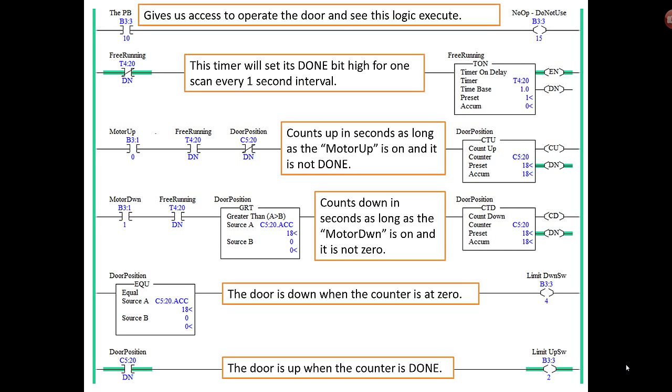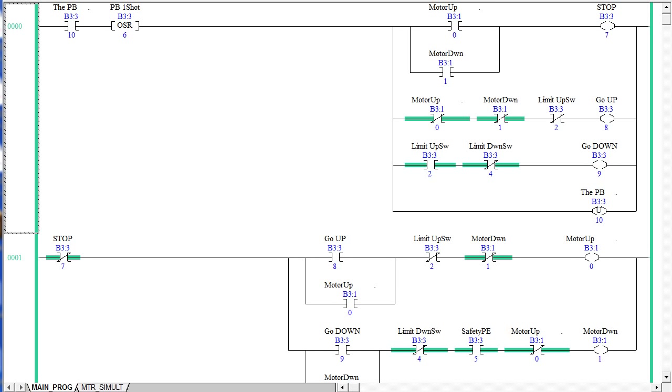So I think what we're going to do now is go to Micro Starter Lite and actually execute this code live for some entertainment. Okay, I tried to fit the active ladder view as large as possible in my recording window. And what you're looking at is the previous code, the single push button using the one-shot instruction to determine whether the push button means stop, go up, go down. Then of course the additional branch to clear that push button so you don't have to retoggle it.